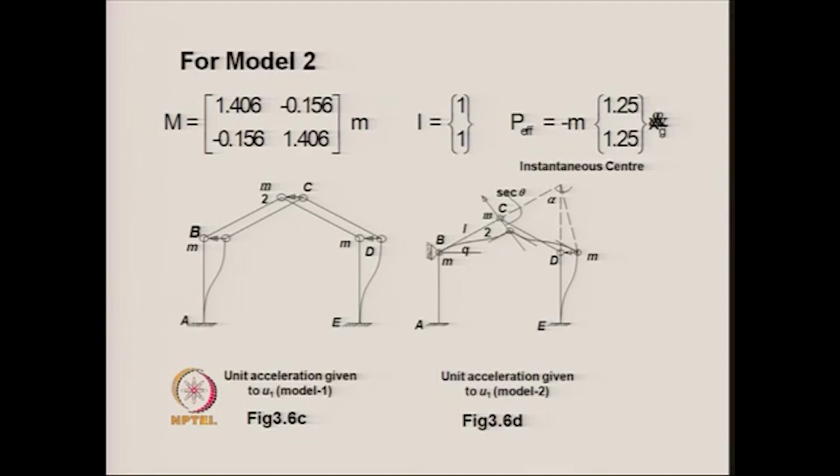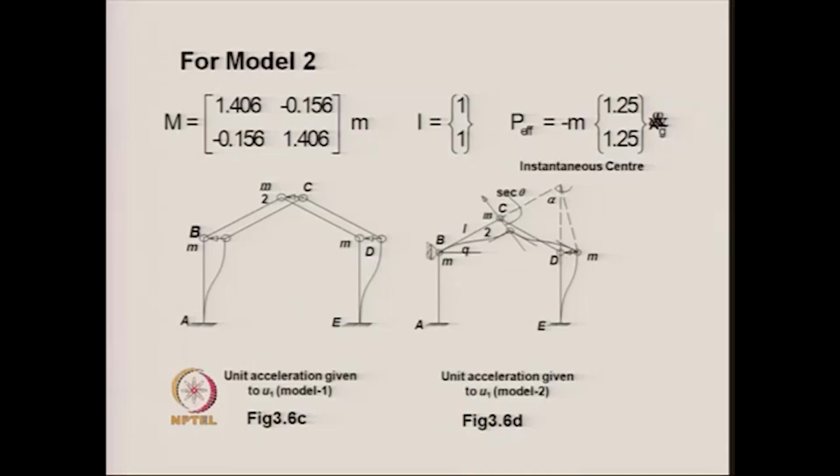When these two components are added together, we can see that the total mass for the case of the same excitation at the two supports turns out to be 2.5 m. So, that is how one can calculate the mass matrices for the different types of degrees of freedom that can be chosen for a pitch roof portal frame.